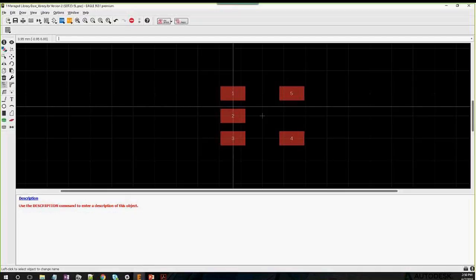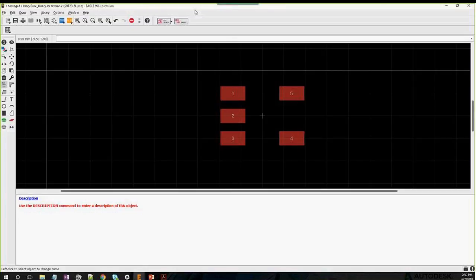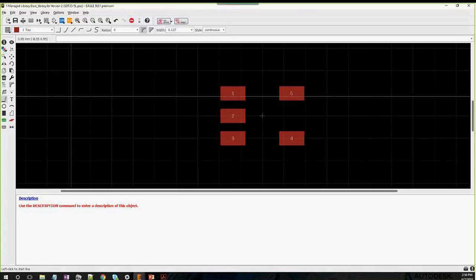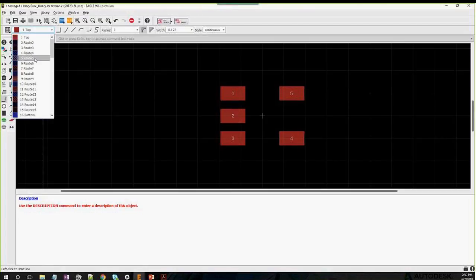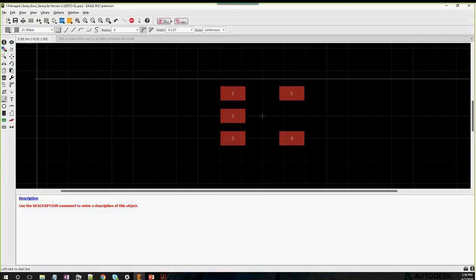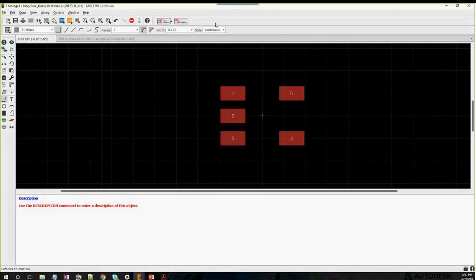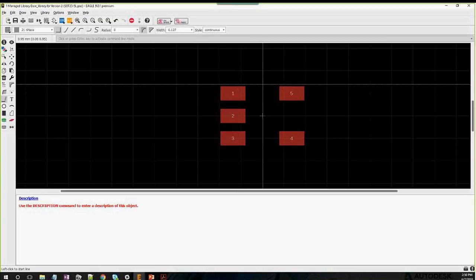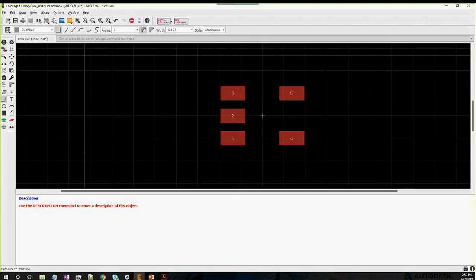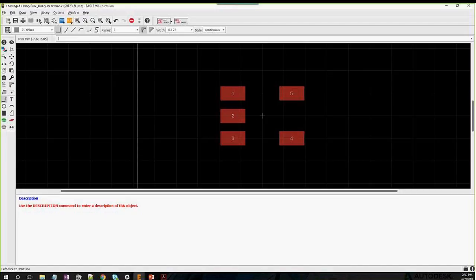And then the height, 3.05 divided by 2 is 1.525. Okay. So what we can do is go ahead and add the silkscreen for it. I click over here, make sure we're on the right layer, which is going to be T-place for this. Okay, thickness, we would want it to be, that's okay, that's a good thickness. Okay, and now what I can do is Control L and start typing in the command line to different points.